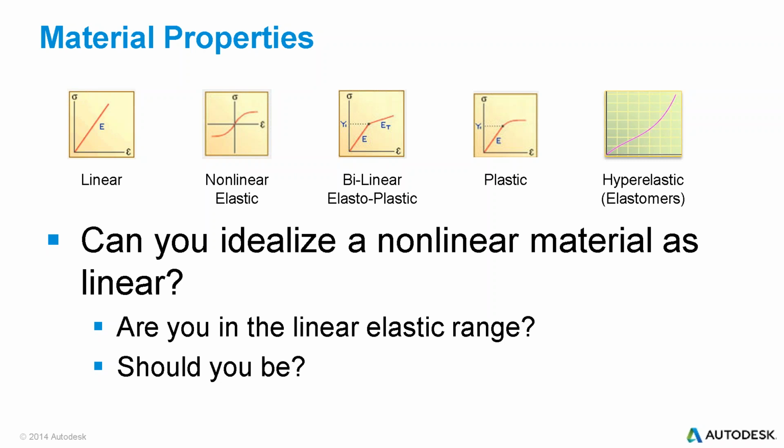Well, no, not necessarily. You could run it as a linear analysis to run a sanity check. Make sure you've got your constraints properly set up, make sure your loading conditions are accurate, make sure it's behaving the way you expect it to. I wouldn't necessarily trust the end result numbers because you would be working with a nonlinear material or a nonlinear situation such as a large deformation, but at least it's a very quick sanity check that it's moving the way it should, it's fixed the way it should, it's behaving the way it should. I just can't trust those amounts until I change to a nonlinear analysis.